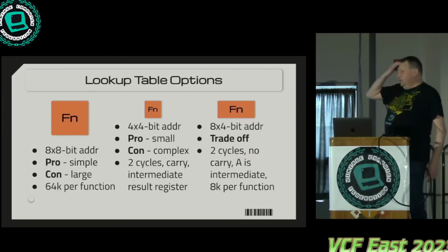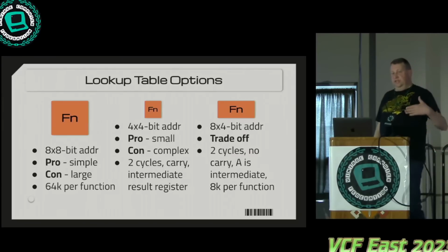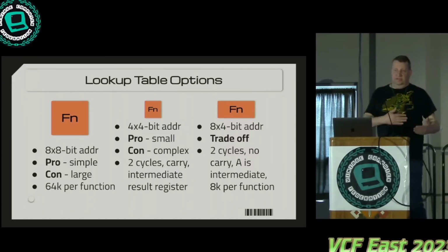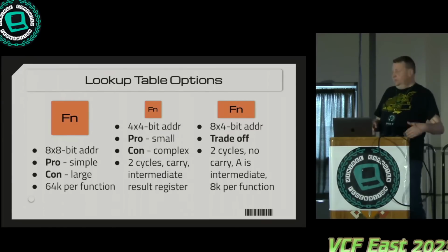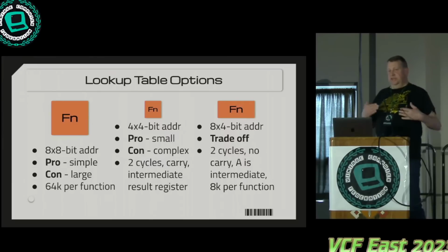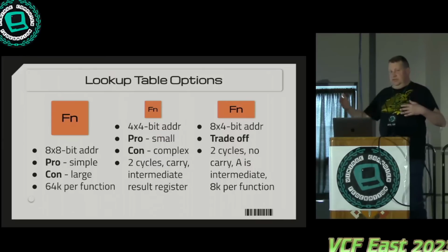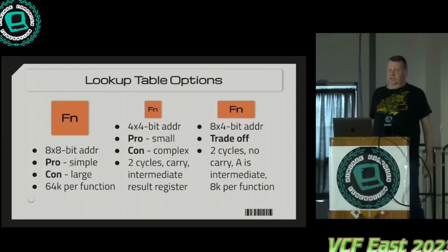And so you can actually just treat one of the bytes directly. So the accumulator goes in as an 8-bit value, and then the other input is split into 2. What I do is add the first half using a 4K table. The result goes back to the accumulator, and then you recycle it to do the second half. You actually have to have a different table to do that, because you have to take into consideration you're shifting up by 4.